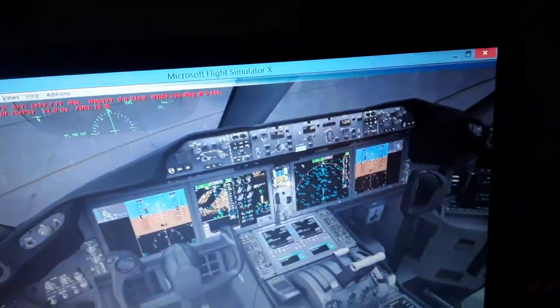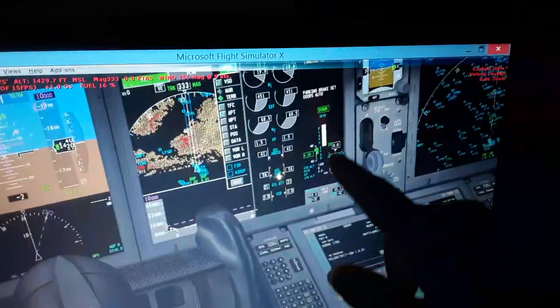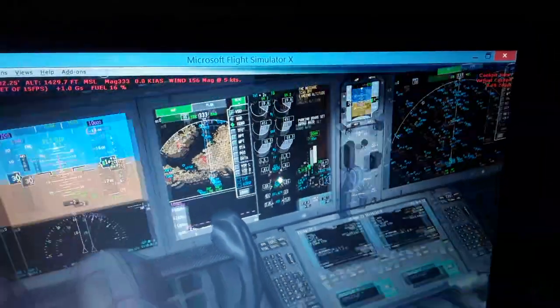The FADEC also control, monitor, and do other things like control the outflow valves of the 5th and 9th stage that supply over here the cabin pressurization. As you can see, I'm gonna show you cabin pressurization, hydraulic fluid tanks pressurization.